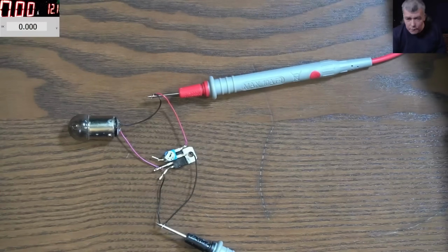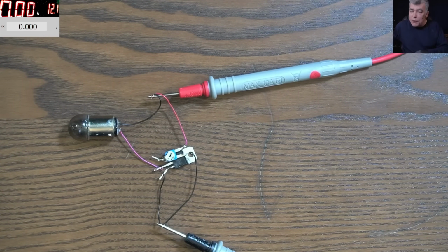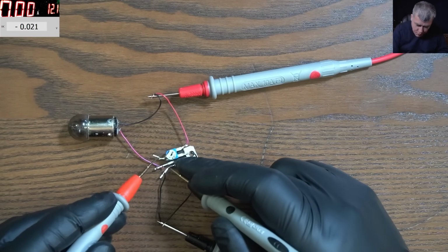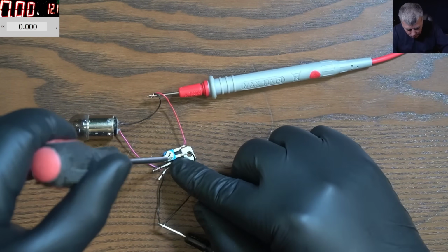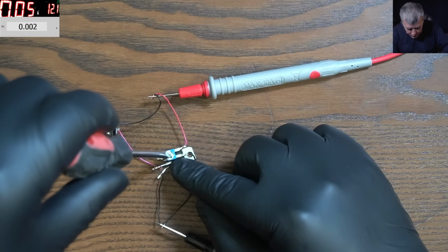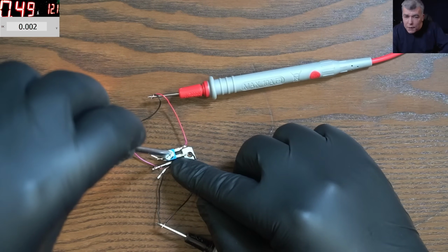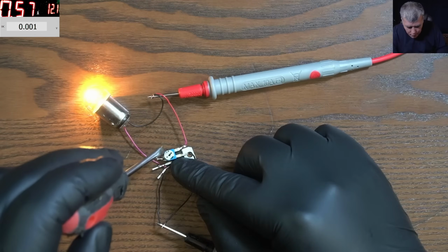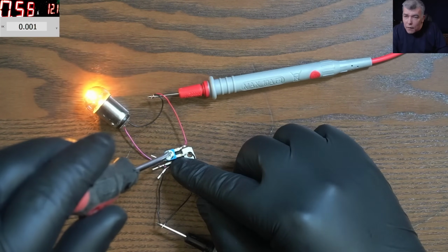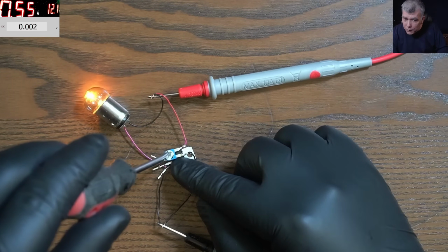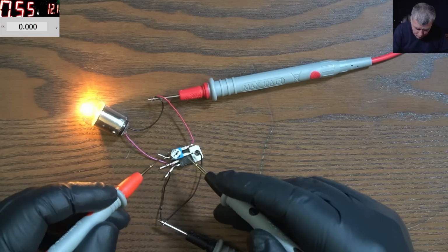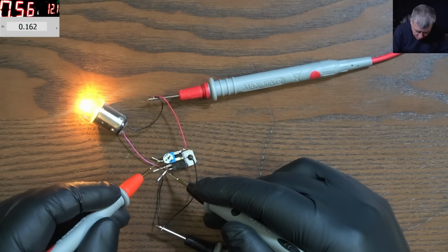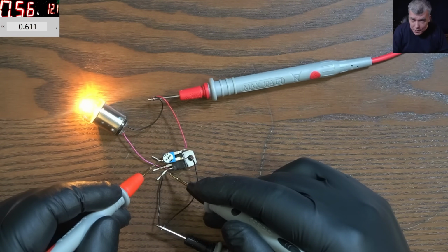Now let's check together to understand. I will take the multimeter just to check the voltage between the base and emitter. So the base of the transistor, which is this one, to the emitter, and we have 0 volts. Now let's adjust this resistor and see what's going to happen. As you can see, I can easily adjust and set up any output voltage from this resistor. Now let's check the voltage between the base and the emitter. Emitter and base, we have 0.6, you can see on the screen.